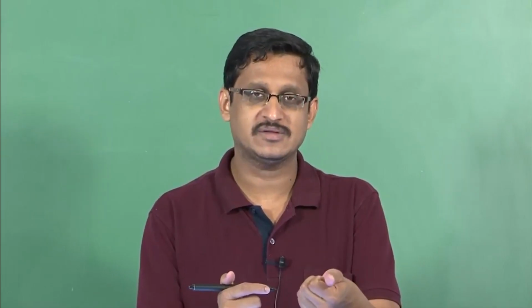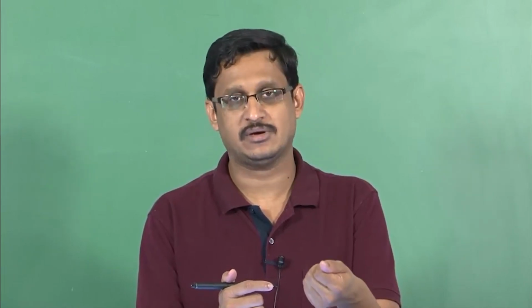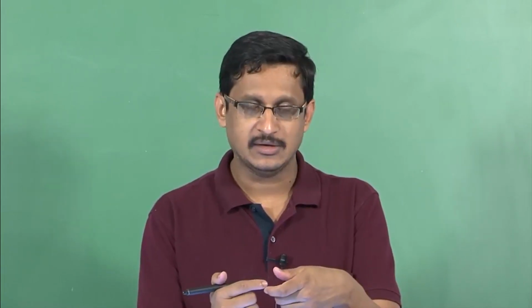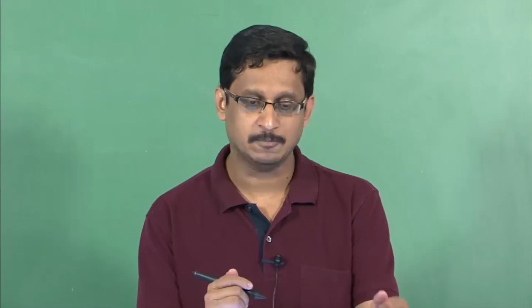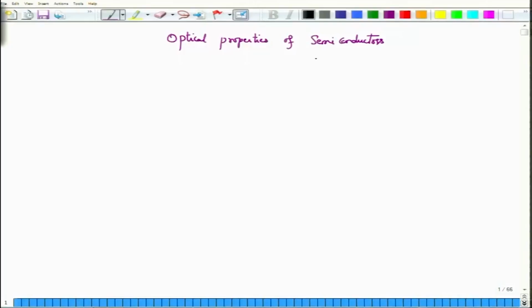So what we mean by this is that all that is sufficient to create pumping in semiconductor laser diodes is to actually have a current and forward bias the junctions that are involved. Okay. So from this big picture, it is very clear that junctions are going to play an important role, and we will look at what happens when you bring two different materials together and how they can be used for lasing. But before that, let us first look at what type of semiconductors are actually suitable as a laser material. In that case, we distinguish two types of semiconductor.